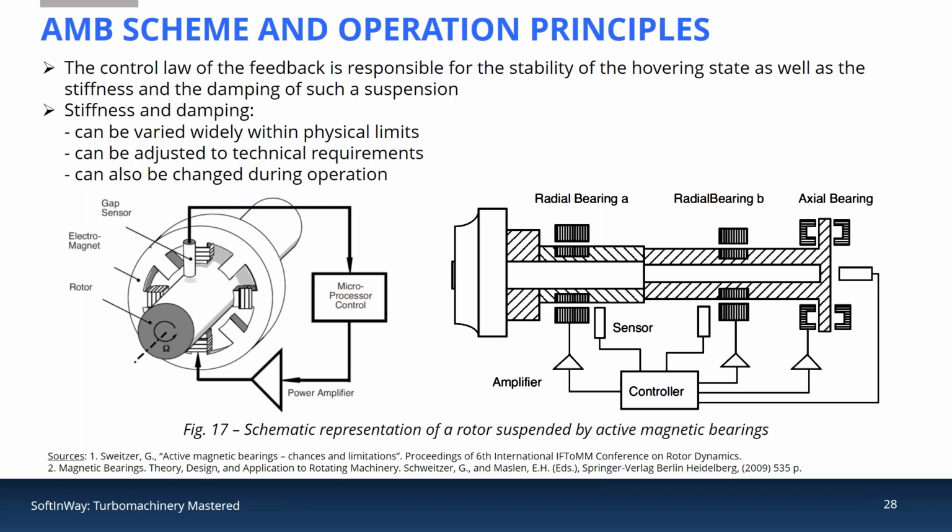The complex structure of active magnetic bearings causes the various failure modes inherent in them. AMBs are usually equipped with backup, in other words, touchdown or catcher ball bearings. This provides rotor runout in the case when the control system fails due to instability or electricity issues.